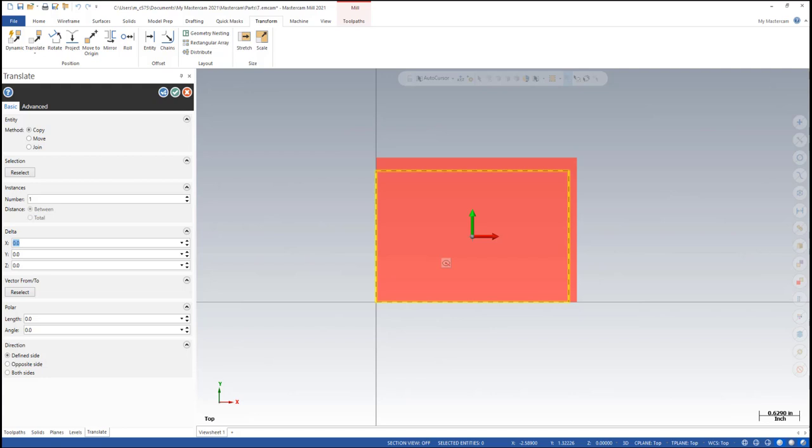So you could figure it out yourself. You can also perform mathematic operations in data entry cells. You could type 1/8/2, or you could type 1/16 or whatever, but once you hit it, it'll do the calculations for you. So it applies that shift. And then in Y, we were 200 thousandths oversized, so we need to shift by 100 thousandths, so 0.1.